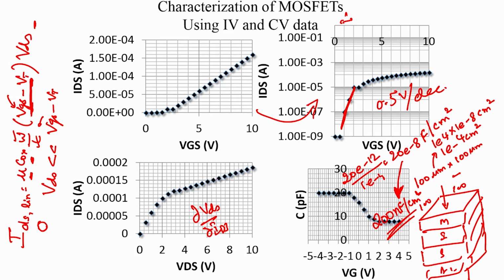Let us say that we keep one point here at 0.0015 and the next point here, close to the edge, which is say 0.0018, which means the difference is about 0.0003. Okay, so the difference in the currents is of the order of 3 e minus 5. So, that is the delta I, and that happens for a voltage difference of about 3 volts.